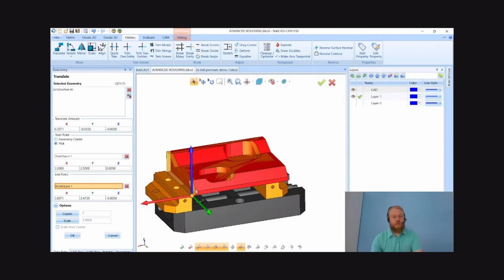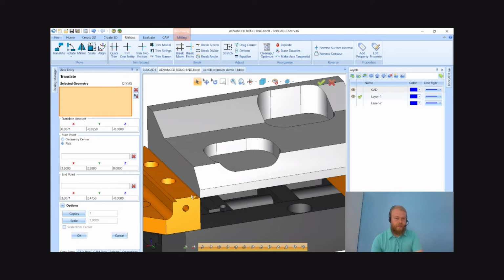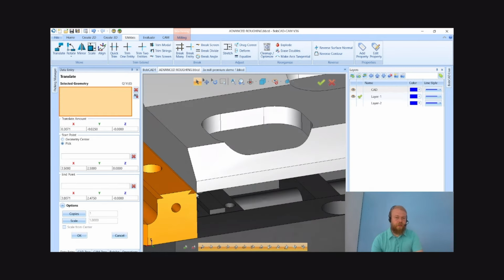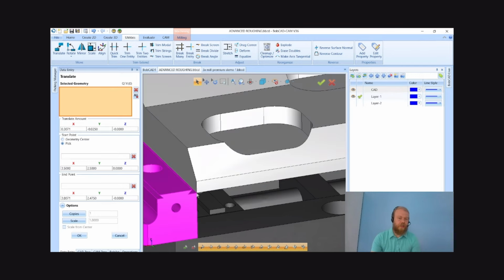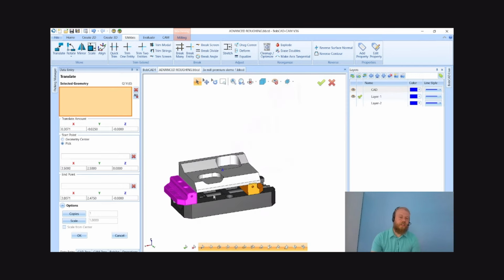You could say, like in SolidWorks, those 2 points would be coincident. Another term in SolidWorks is setting up mate references, so that you're mating the 2 points together at a certain location to make them coincident. You could set them at a certain distance. You could always translate the geometry out a little bit in X, Y, or Z after that.